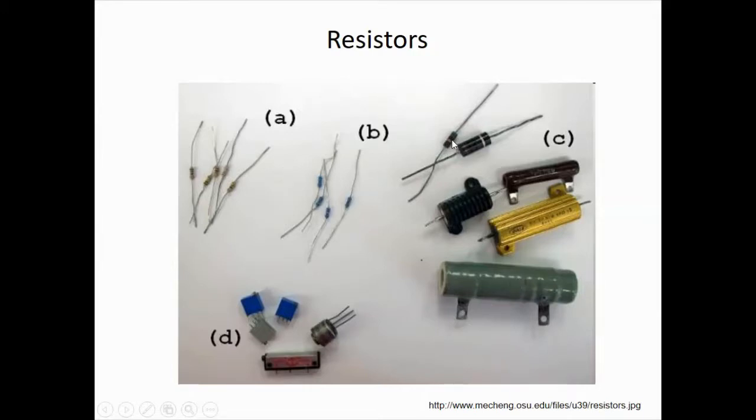If, for example, you try to pass a current through this resistor that generates a power of, let's say, 3-4 watts, then this resistor will simply burn. Some fumes will come out and it will burn, and it will of course become an open circuit very quickly. This resistor probably can carry about 2 watts. This can carry many tens of watts.